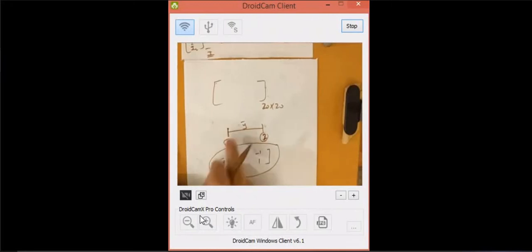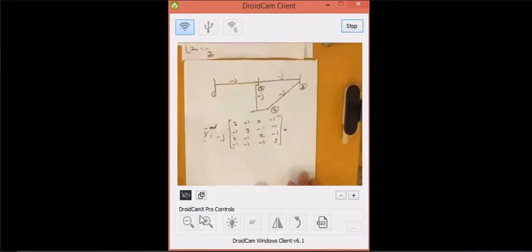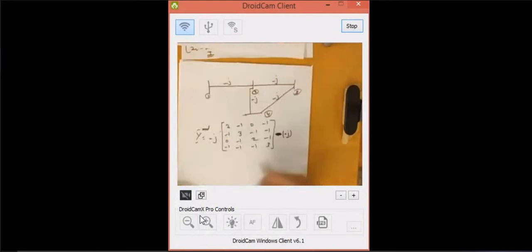So let me apply it here. Now we say that we are removing, okay, this means that minus, removing the line between 1 and 4. What is the admittance of the line between 1 and 4? It is equal to minus g. We said here 1 minus 1, minus 1 and 1, so this is connected between 1 and 4.